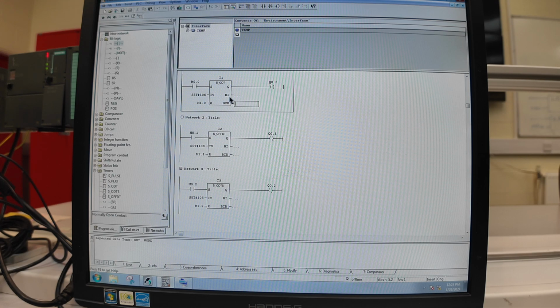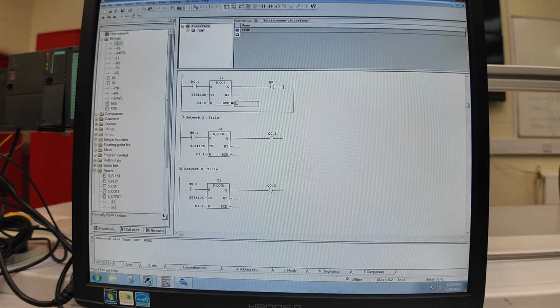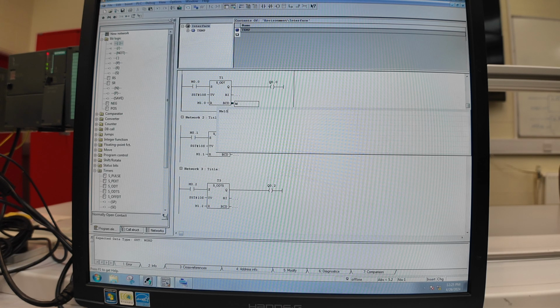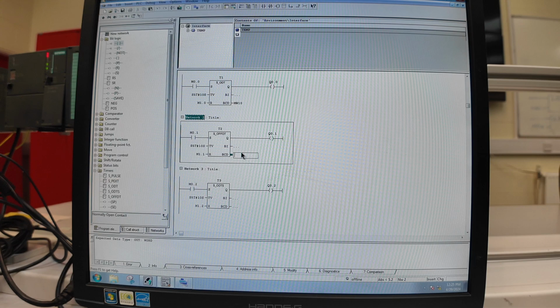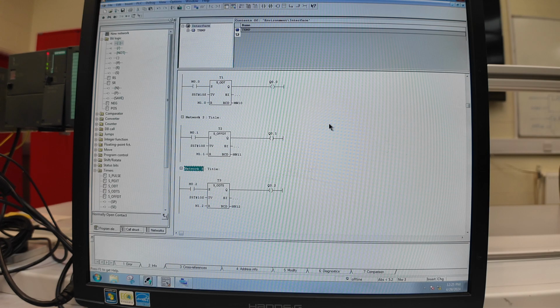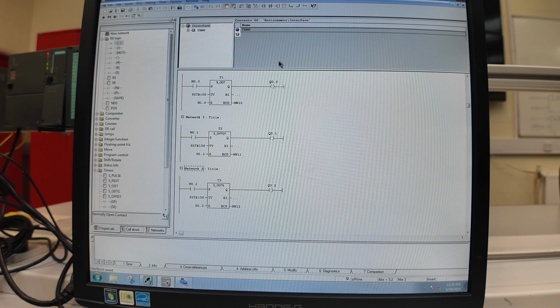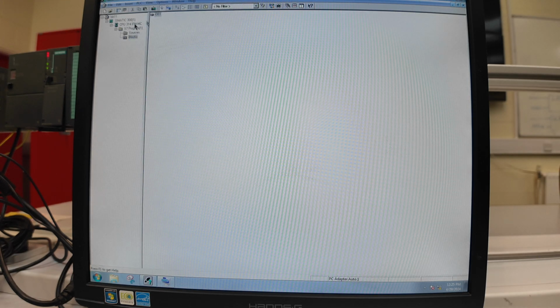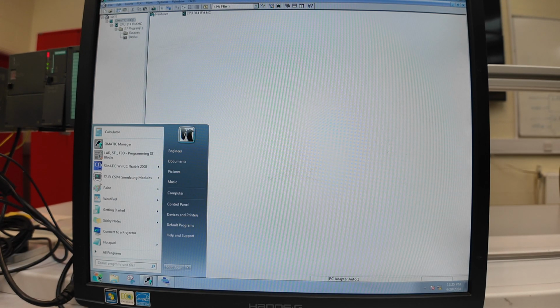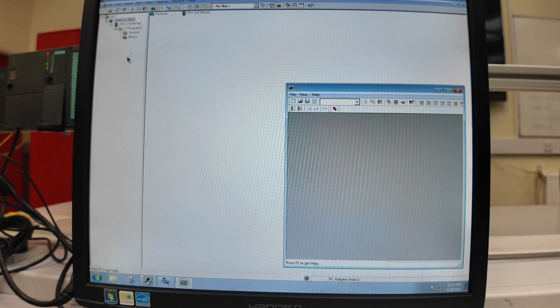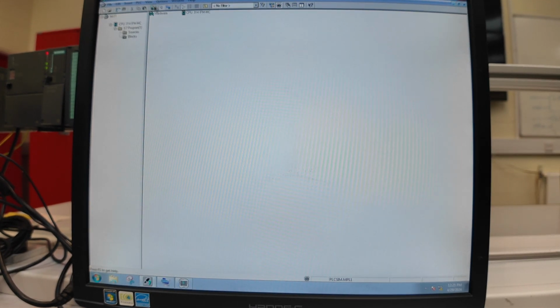So these both outputs, BI and BCD, just give us the remaining time. So I'm going to use here a memory word. Okay, that's it so far about the timer. So now we go and test it. We open the PLC. We download our file.